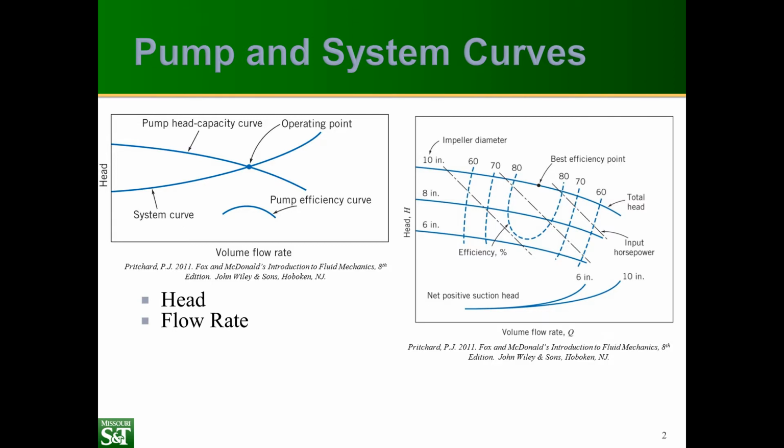And then you have one more check. You need to make sure that the net positive suction head available is enough. It's got to be at least 10% higher than the net positive suction head required.